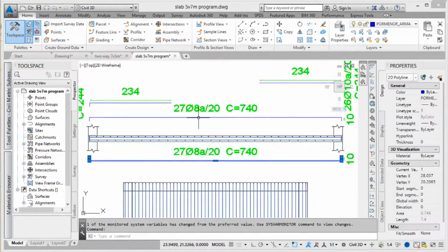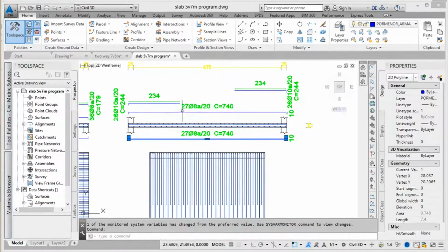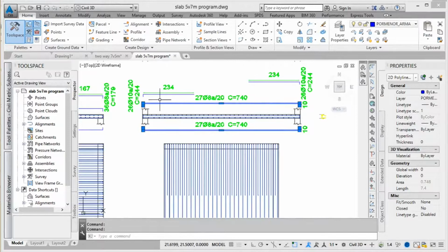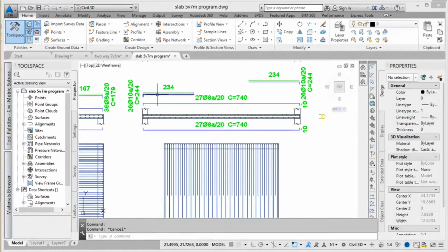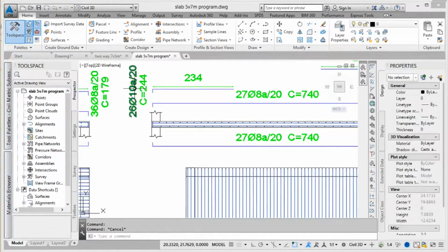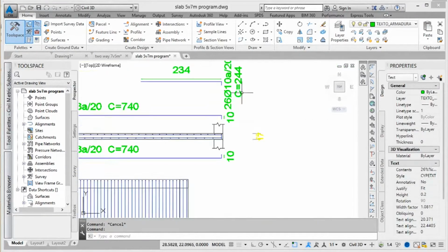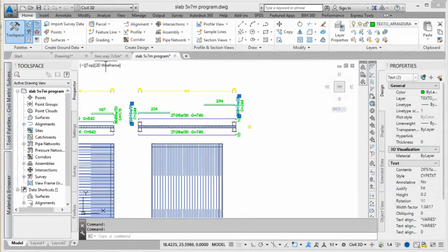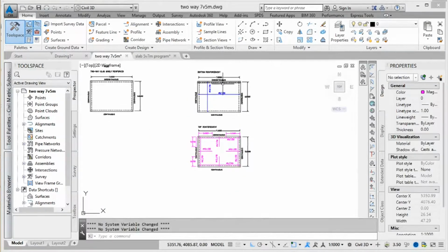The software continues using the minimum steel here, the minimum reinforcement on the half span. You always consider the combinations of many factors and wind. This is why you put the diameter of 8, 20 going from one side to the other. Otherwise it will be the same. Okay, on the top reinforcement 2.34 length, and on this side was a diameter of 10 spaced by 20. On the other side, a diameter of 10 spaced by 20 centimeters. And what we calculated was exactly the same.